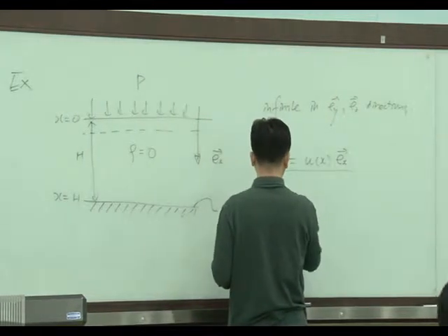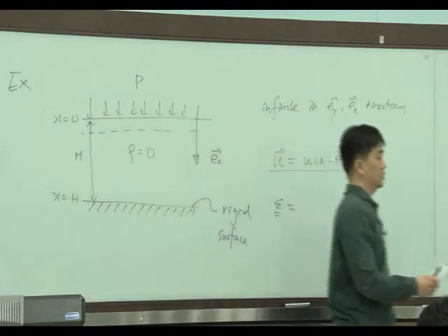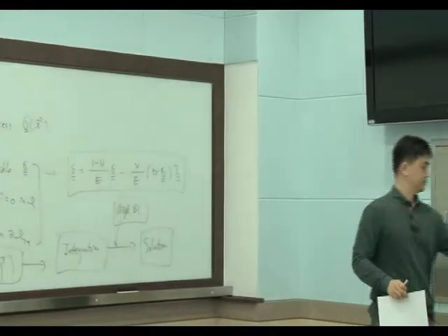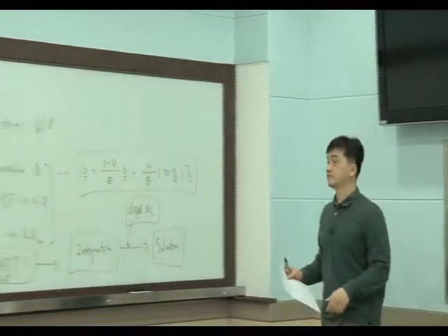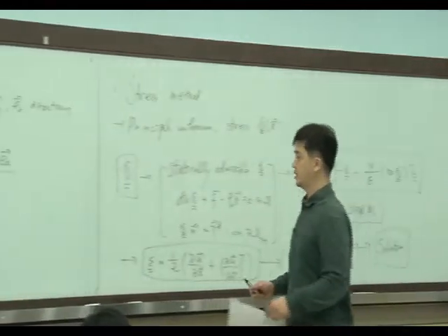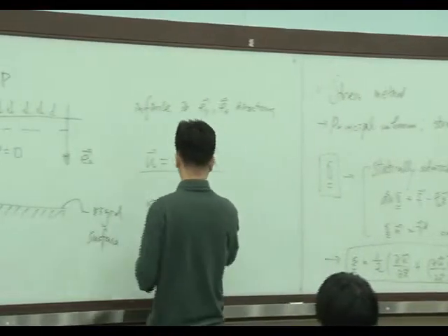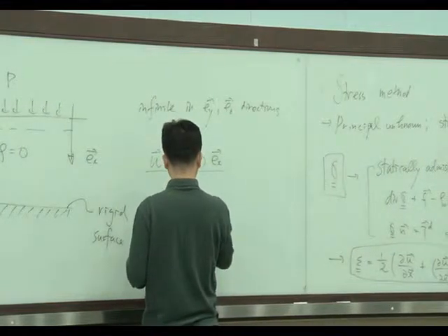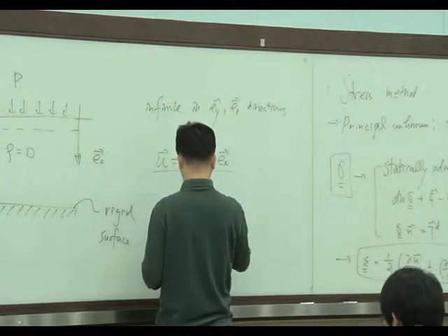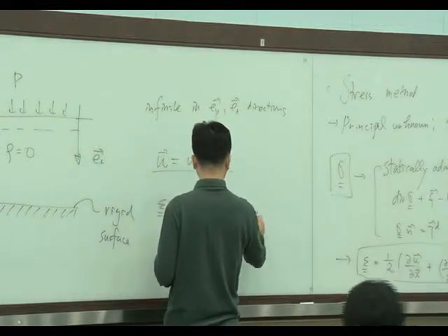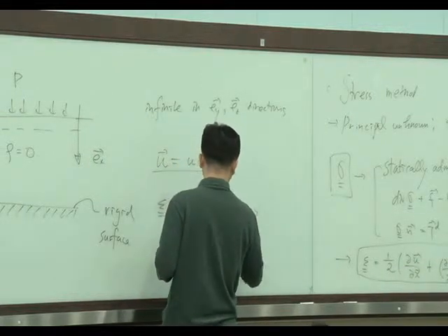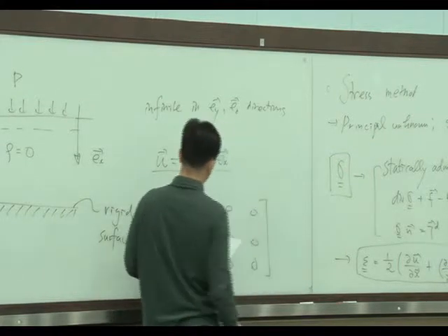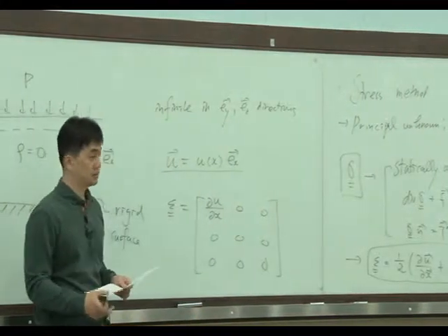Then, second is the strain. We can calculate the strain. The strain field will be very simple: u,x, 0, 0, 0, 0, 0. There will be only strain in the x direction through the thickness.